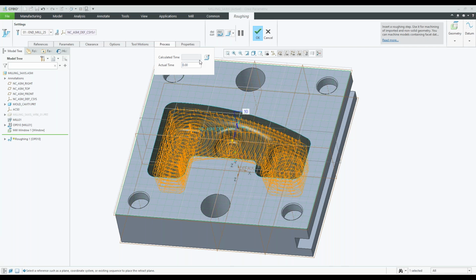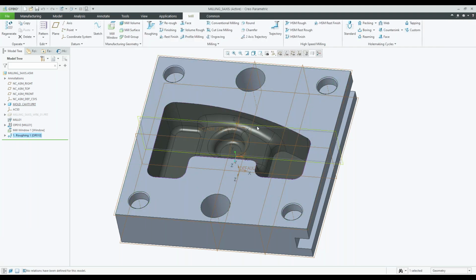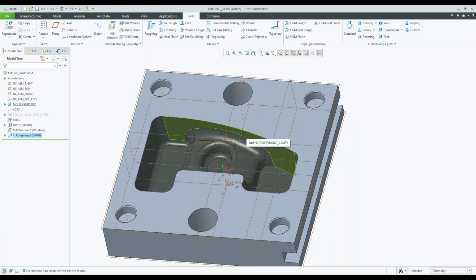So what I normally tell the guys is you'll get a feel for the machining time. If there's a lot of rapid moves, maybe add 10%, 5%, and that will give you a more accurate value. But this is just cutting time, so actual shaving time, where you're creating shavings. Okay, so we've done that. So let's quickly go on to the next one.